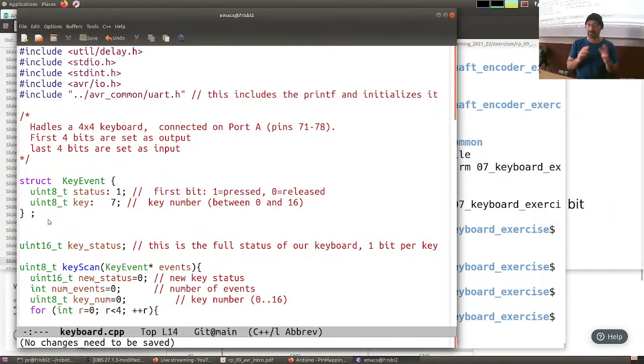They are very useful, these bit structures, when you want to access the flags of a register, because you could define a register as a struct, where the first bit corresponds to the first pin, the second bit maybe corresponds to another pin, and you can call these pins by their function. Sometimes the pins of a register have a specific name. Like in case of the UART, there will be a bit that tells you whether a character has been received or not. So in this way, instead of playing with bit masks, you can just read and write a bit directly. All right.